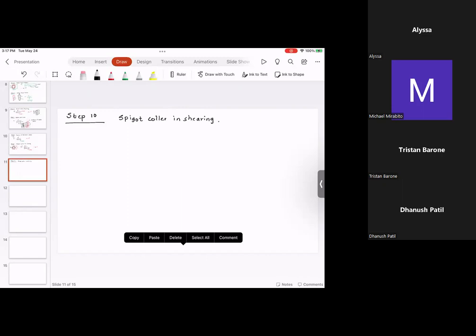And we already did something like this. So tau is equal to P divided by pi times D2 times T. So if you think about what is happening, this is D2 and this distance is T. So think about it like it's a circumferential shear.